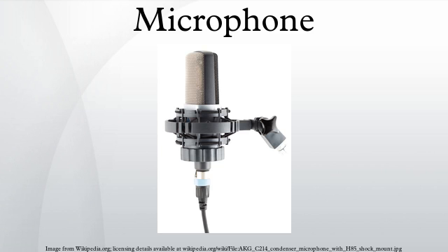Omnidirectional. An omnidirectional microphone's response is generally considered to be a perfect sphere in 3 dimensions. In the real world, this is not the case. As with directional microphones, the polar pattern for an omnidirectional microphone is a function of frequency. The body of the microphone is not infinitely small and, as a consequence, it tends to get in its own way with respect to sounds arriving from the rear, causing a slight flattening of the polar response. This flattening increases as the diameter of the microphone reaches the wavelength of the frequency in question. Therefore, the smallest diameter microphone gives the best omnidirectional characteristics at high frequencies.